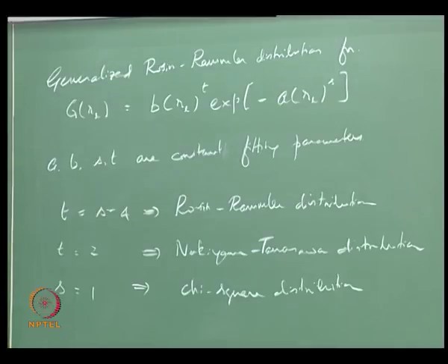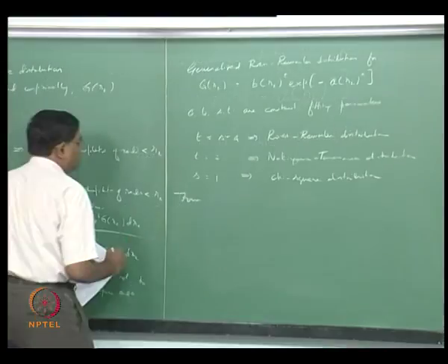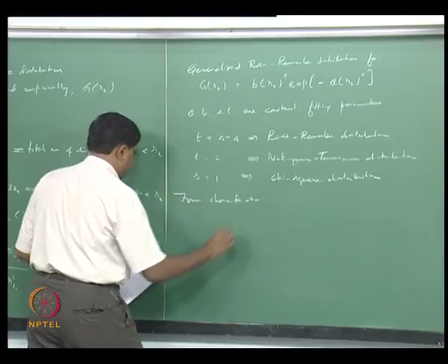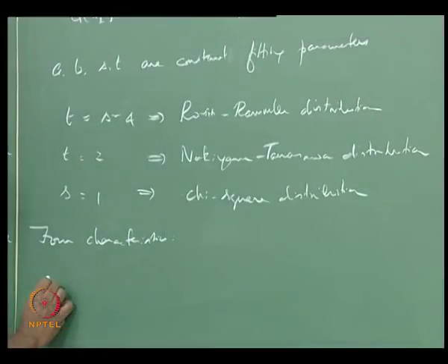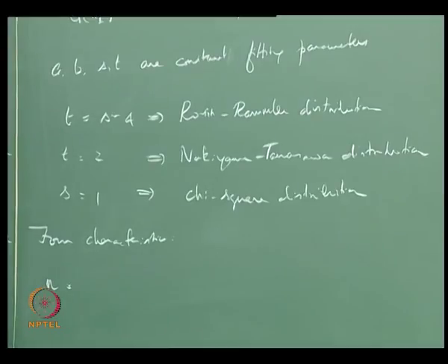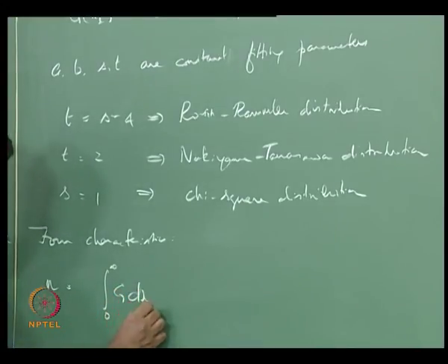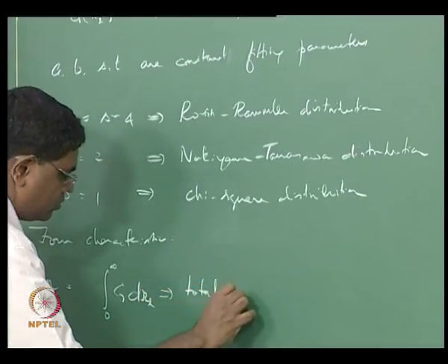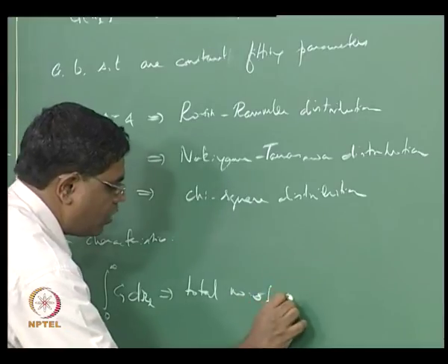What we should be looking for in trying to fit curves is 4 conserved parameters. So essentially the 4 characteristics that we should be looking for. N is the total number of droplets, which is something that we saw, but here we try to take all droplets, so the integral from 0 to infinity of G dRL, the total number of all droplets.